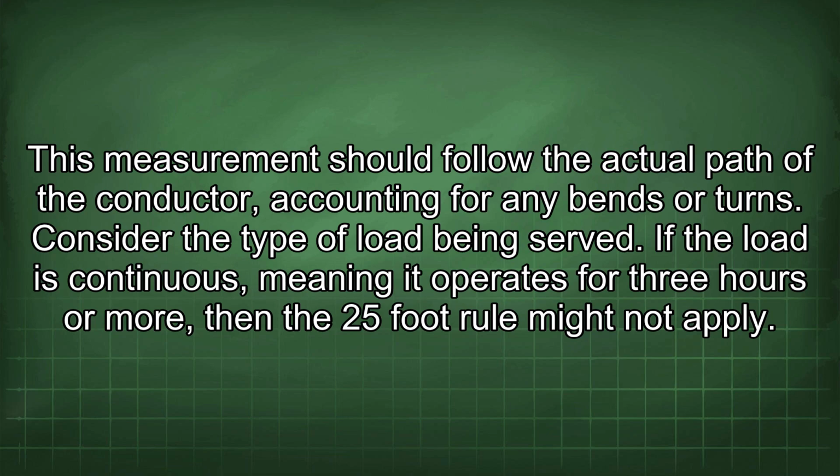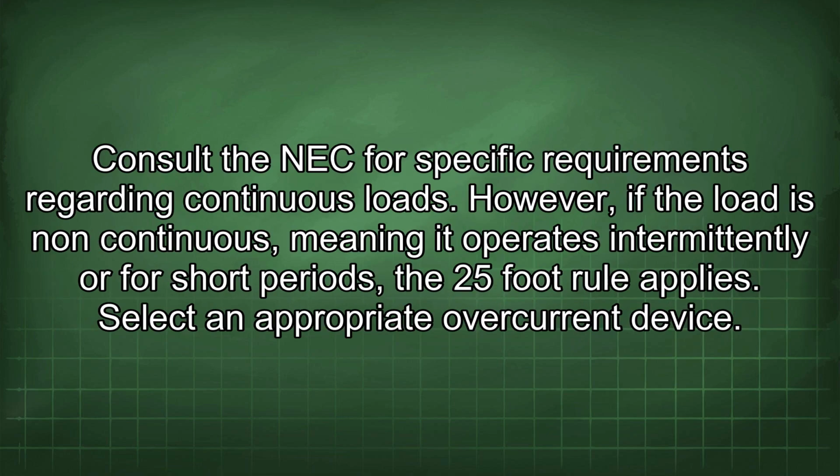Consider the type of load being served. If the load is continuous, meaning it operates for 3 hours or more, then the 25-foot rule might not apply. Consult the NEC for specific requirements regarding continuous loads. However, if the load is non-continuous, meaning it operates intermittently or for short periods, the 25-foot rule applies.